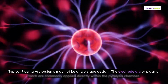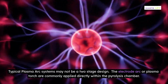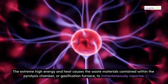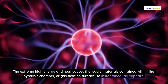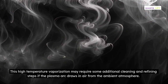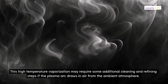Typical plasma arc systems may not be a two-stage design. The electrode arc or plasma torch are commonly applied directly within the pyrolysis chamber. The extreme high energy and heat causes the waste materials contained within the pyrolysis chamber, or gasification furnace, to instantaneously vaporize. This high-temperature vaporization may require some additional cleaning and refining steps if the plasma arc draws in air from the ambient atmosphere.